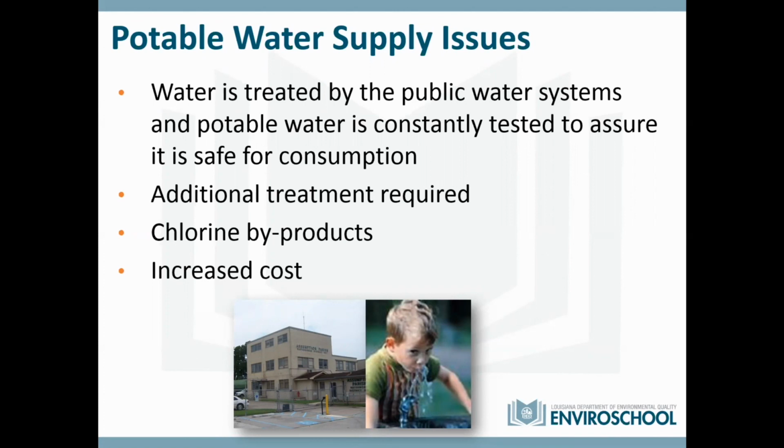At least it's safe. But if there's a lot of sewage in this water body, like Bayou Lafourche, it will cause the water system to do more treatment. And generally, for disinfection, they use some sort of chloramines. And that chloramines will actually bond with the organic materials naturally in the water, but also there's more of it in the water because of the sewage.